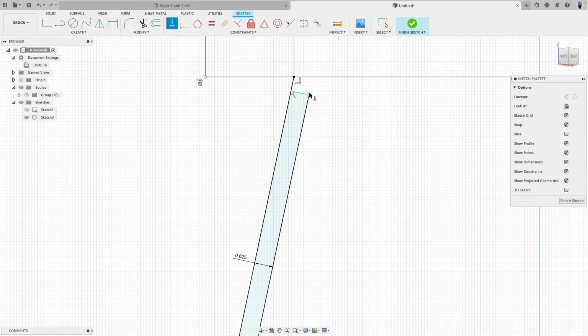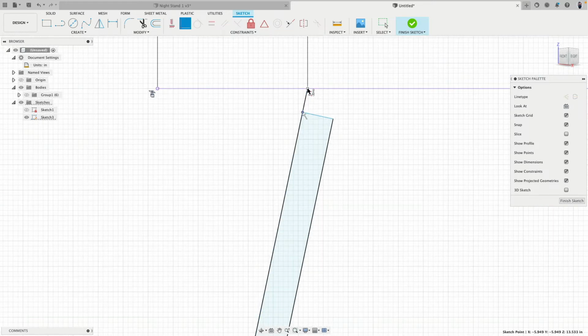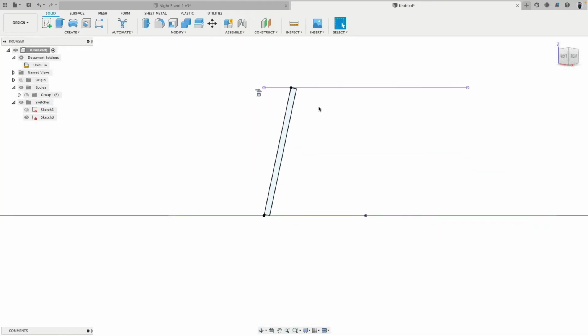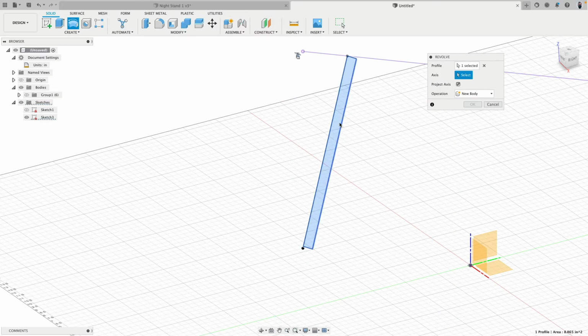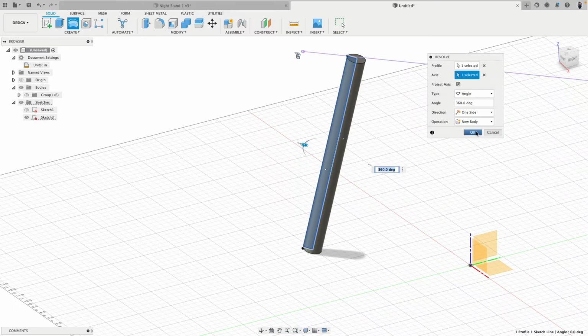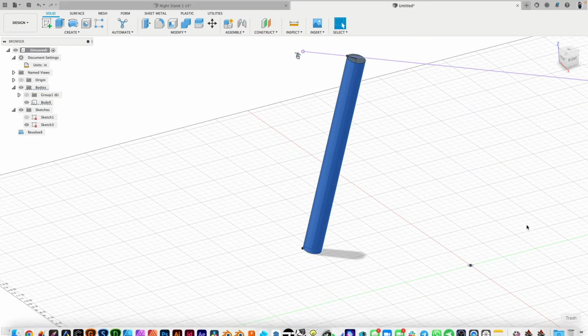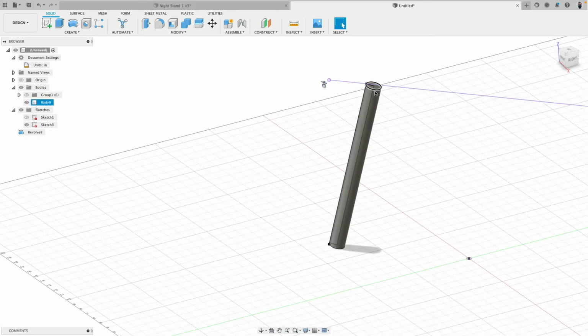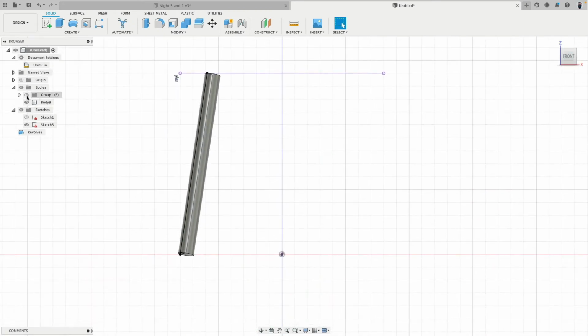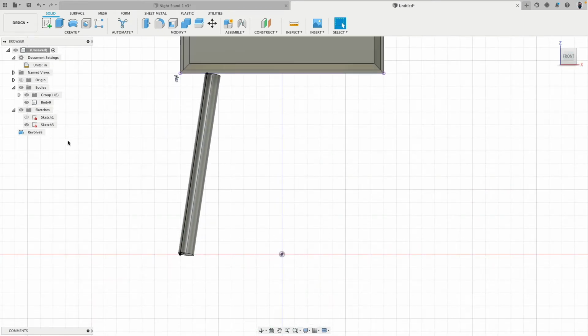And here, yeah, how do we do this one? I will simply do it this way. So this point coincident to there. So we just glue it, pin it to there. Cool. So there's our leg. This leg now, I will, with the revolve command, select the profile, select the axis, do my leg. So 1.25 for the diameter. Yeah, this is perfect. This is really good. That's exactly what I want. Cool. Okay.